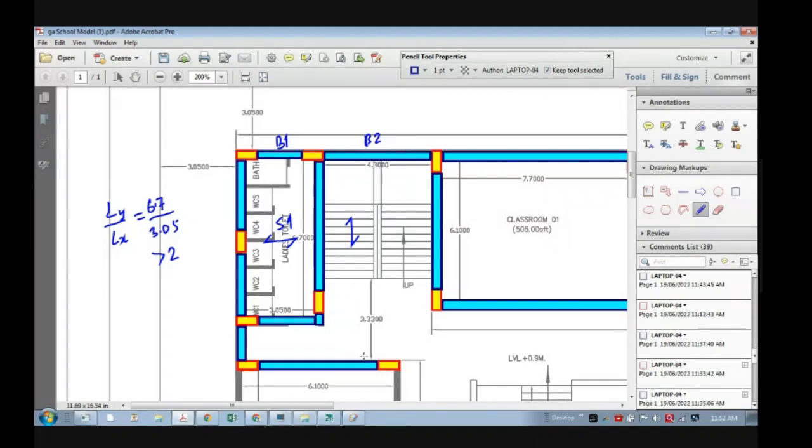Now where will the remaining load go here? For the remaining load, sir, we will have to give a beam along the same flight. So see, I don't have any beam over here which will take the one-way load here. Half load will go here on B2, but here also we need something. So that means now I want a beam. So whenever we do planning, in between some such requirements keep developing. That's why I told you start somewhere. Start with anything, think over it later. Now I don't have a beam here to take the load, so I am providing one here.